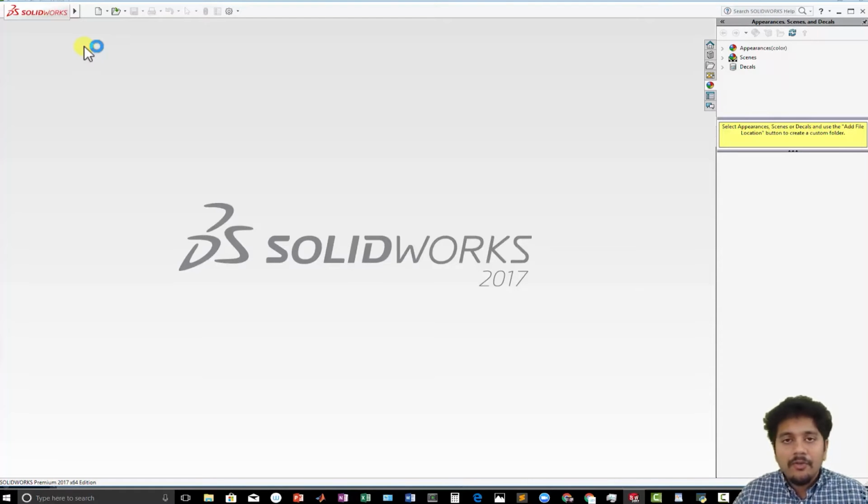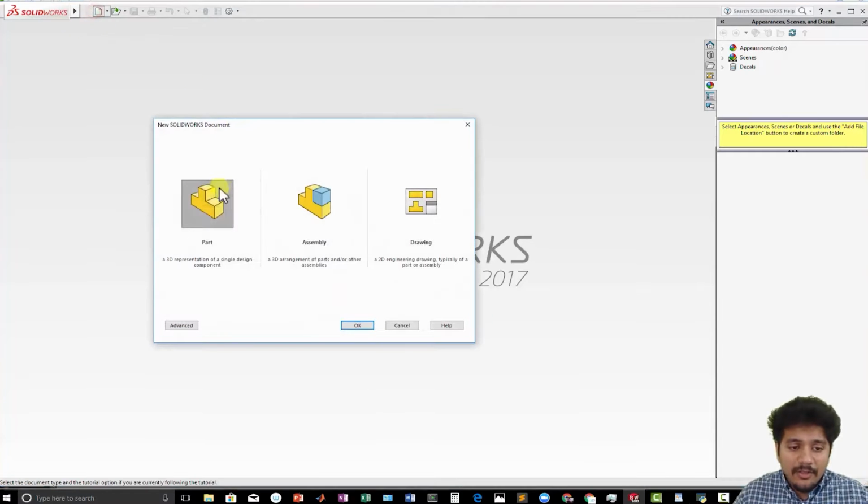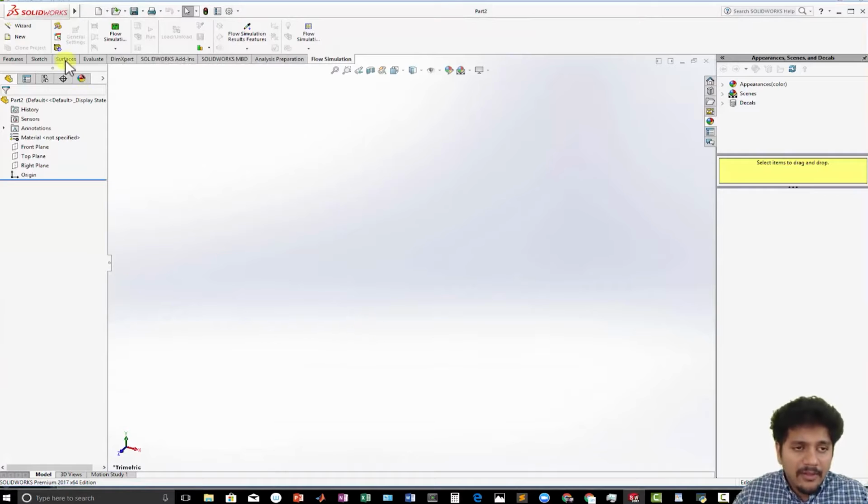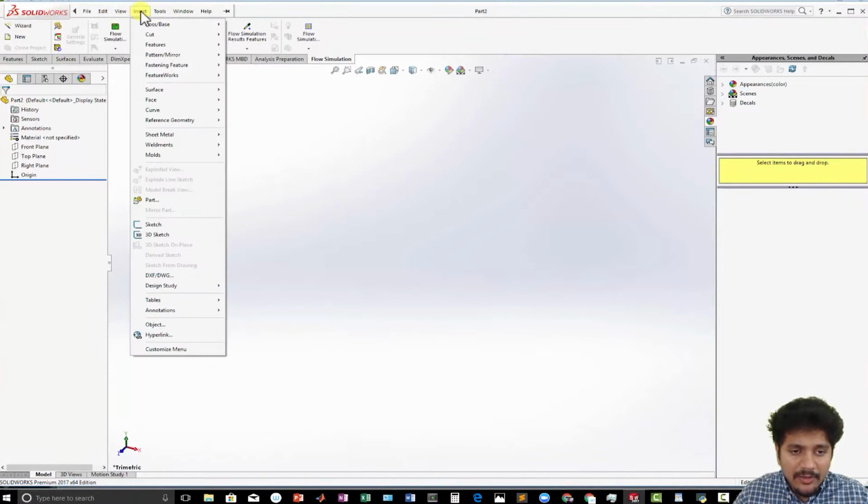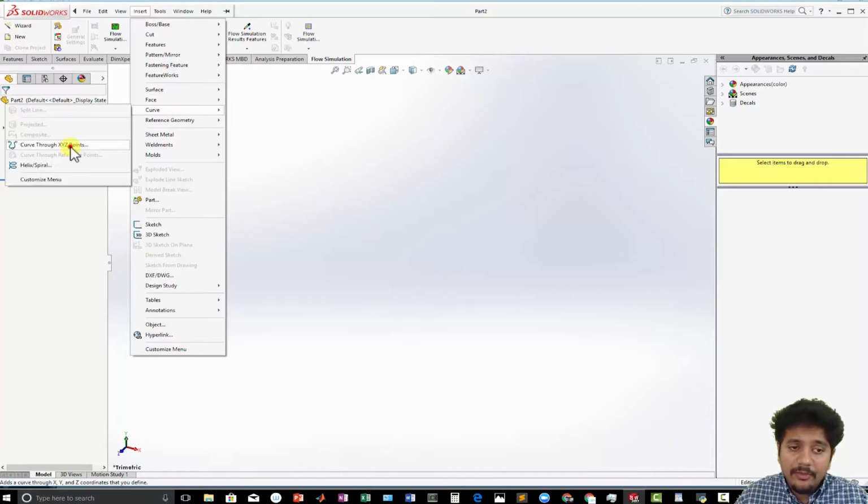In this video, we are going to be simulating a flow over a NACA airfoil. To get started, create a new project and let's create a new part file. And then we're immediately going to go to Insert, Curves, and we are going to select Curve through XYZ points.